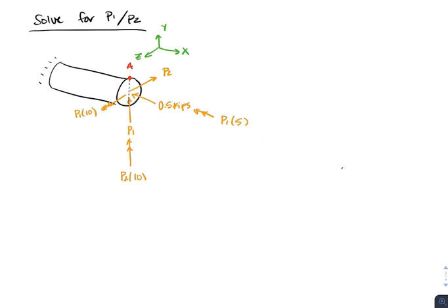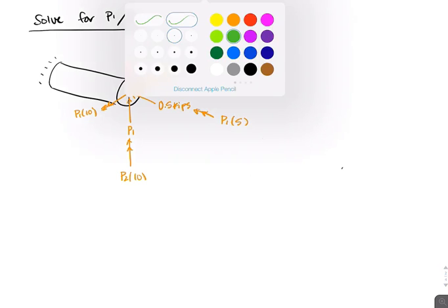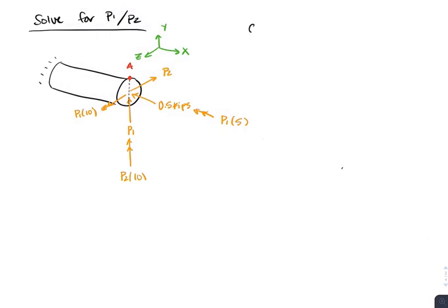If we redraw our stress block for point A, that gives us what we had above, which was a negative 36.5 for our sigma xx. Then we had 0 for sigma xy. Then we have a negative 9.66, then that same thing but positive 9.66, and everything else was 0. This was in ksi. That was what was given in the problem.